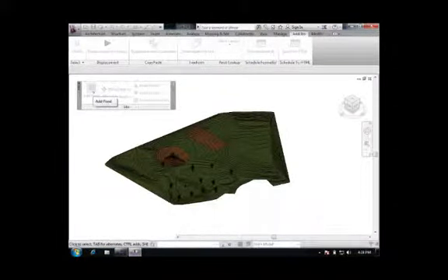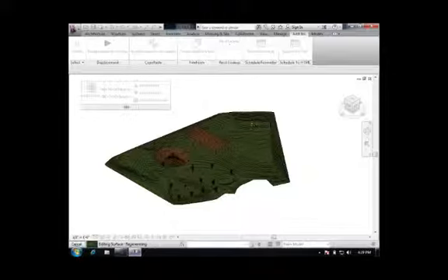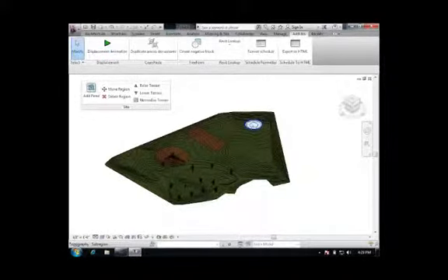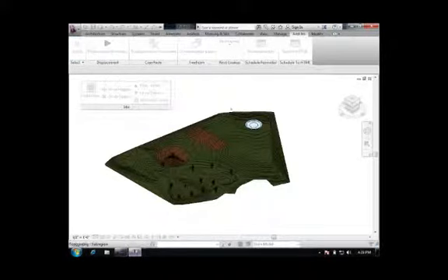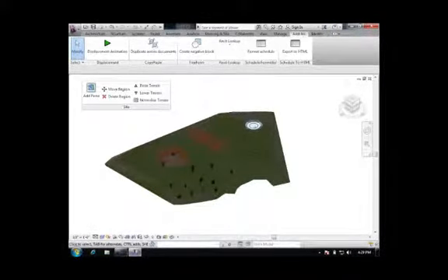I clicked add pond and it's prompting me to select a point. So I'll place the pond right here. You can see in the status bar the progress being made. I have a new subregion on my topography surface. If I ask the terrain to be lowered, it asks me to select the appropriate subregion and lowers that for me.